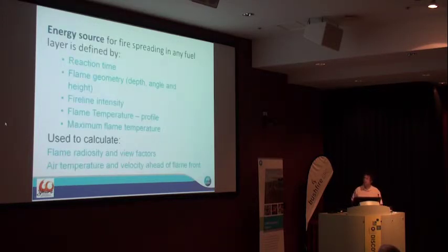So for these, we would like to call it a model system. There's a lot of things we need to know, because essentially we have a fire, and we need to characterize the fire as an energy source, and for that we need to calculate all these properties of the fire: the reaction time or residence time, the flame depth, the flame geometry, height and angle, fireline intensity, flame temperature profile, how the temperature changes with height in the flame, and the flame maximum temperature.